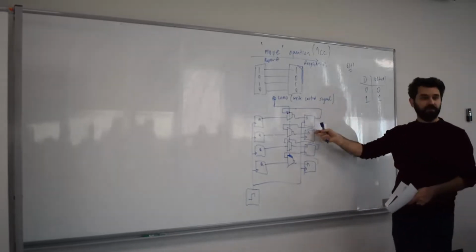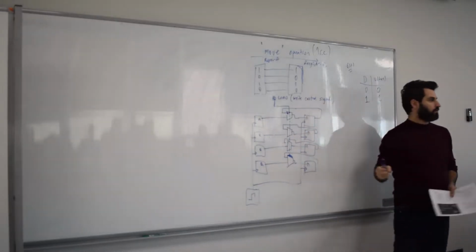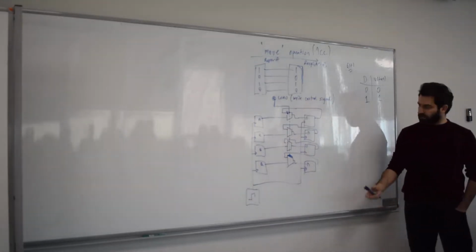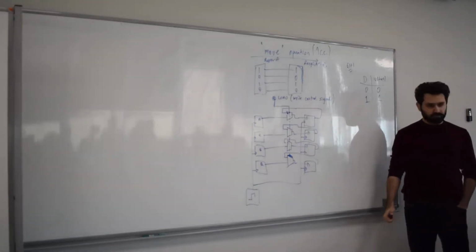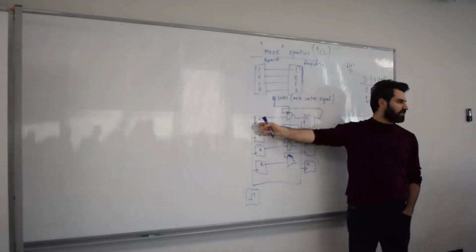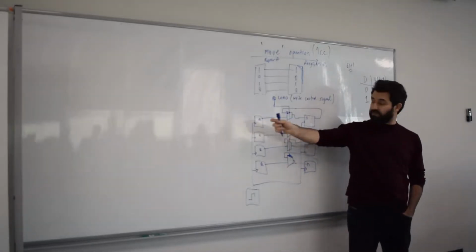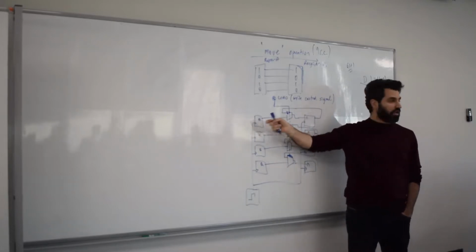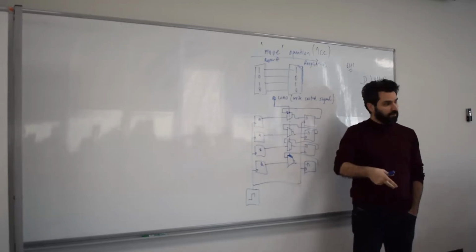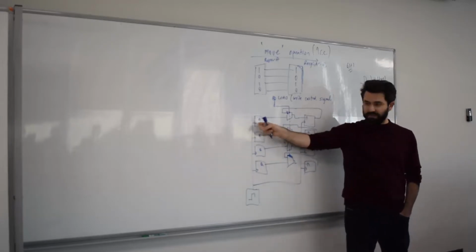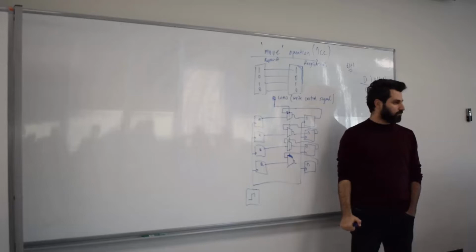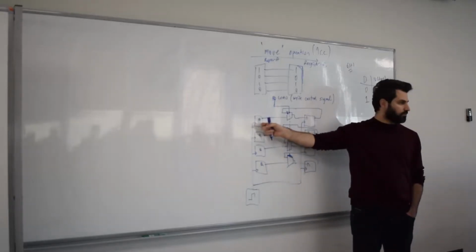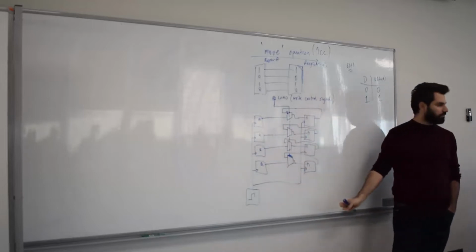Did you understand the mechanism here? Can we use the master-slave approach here? Master-slave is actually inside this cube, right? Inside this flip-flop. Master-slave is used to produce a flip-flop out of 2 D latches, remember? So you can use master-slave inside your flip-flop. Is this a flip-flop? No, this is a D flip-flop. All of them are D flip-flops.